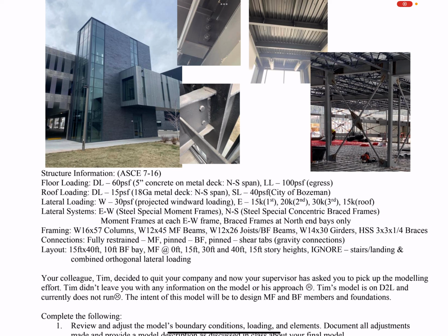All right. North-south earthquake, well, I gave you story forces, right? How much load needs to be put at each one of the floor levels from first up to the roof. Lateral systems, okay? Yeah, lateral system, sorry. East-west direction, we have steel special moment frames. North-south, we have steel special concentric brace frames.